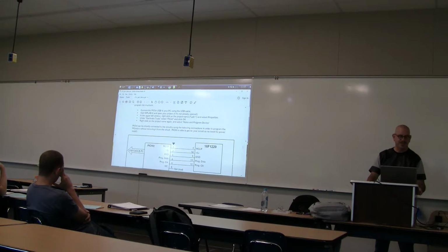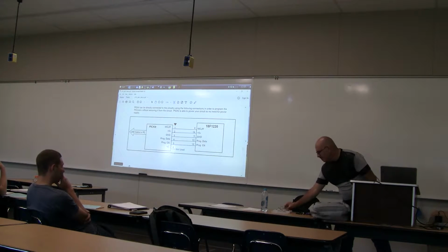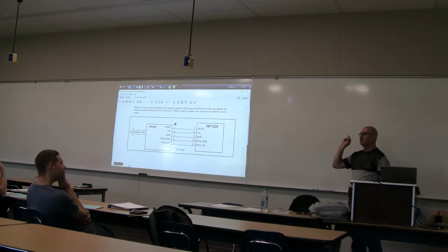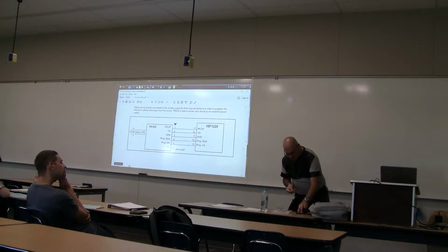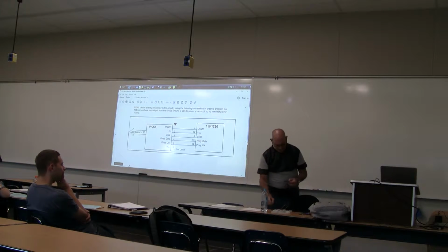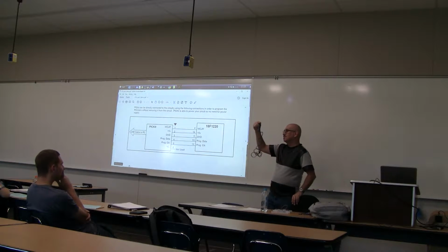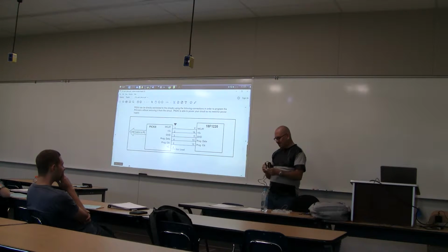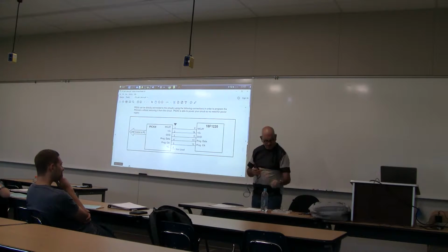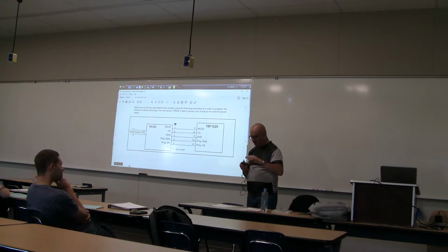After you've done that, you want to actually program this chip with the code that you've written, so that you can actually put this on a proto board, hook up an LED, and have it do its thing. All right. To load a program into here, we have to use a thing called a programmer. So we have a programmer called a PicKit2. And it takes a USB connection on one end, and on the other end we've got 6 holes coming out of here, and these holes will accept these jumper wires. You can just put them in there.